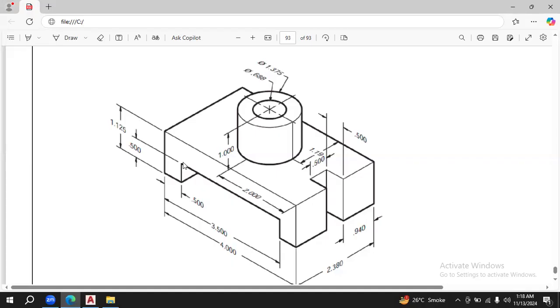For the very first step, I am going to develop this N-shape 2D frame, and then we will apply the press and pull command over it. So for that, if I take this point as my starting point, along the x-axis it is 0.5, then along the z-axis it is again 0.5.